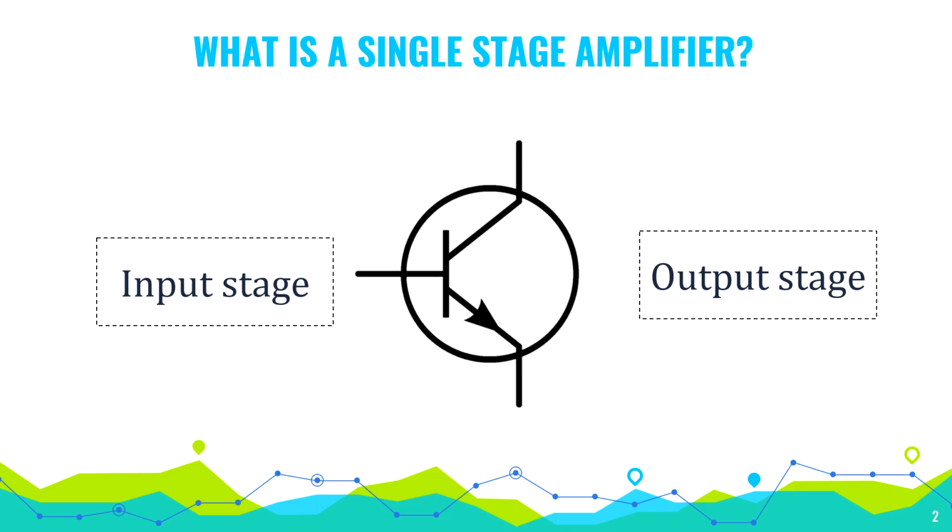To recall, in a common emitter amplifier, input is given to base terminal and output is taken to the collector terminal, while emitter is common between both input and output terminal. For an amplifier to act, a small input signal of base current controls a large output signal of collector current, and that is why it is called as common emitter amplifier.